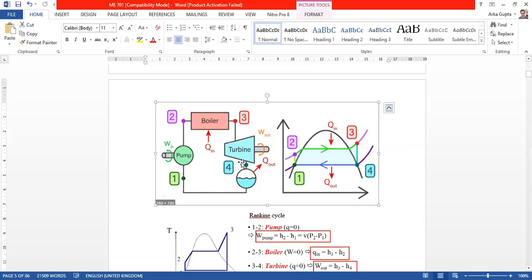So it is very much required that after condensation, the whole steam will become liquid. The pump will operate only through saturated liquid. Okay. So 1 to 2 is isentropic compression or a reversible adiabatic pumping process. 1 to 2 is shown in the TS diagram. At 2 it is liquid, at 1 it is saturated liquid. So it is pumped to the boiler. Then 2 to 3, that whole process is the boiler.